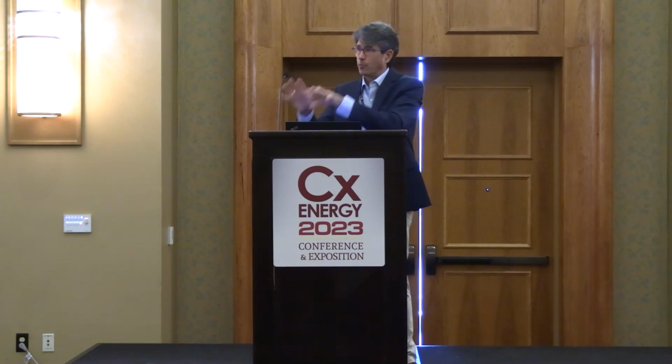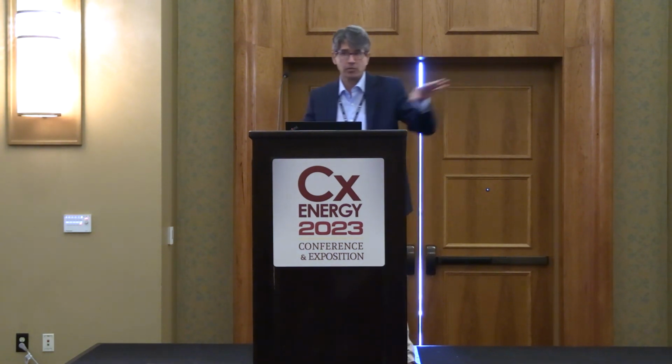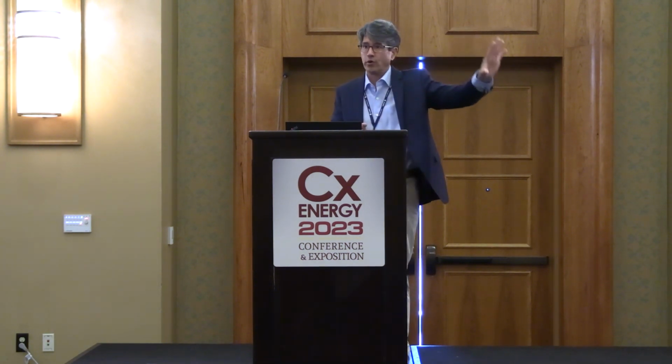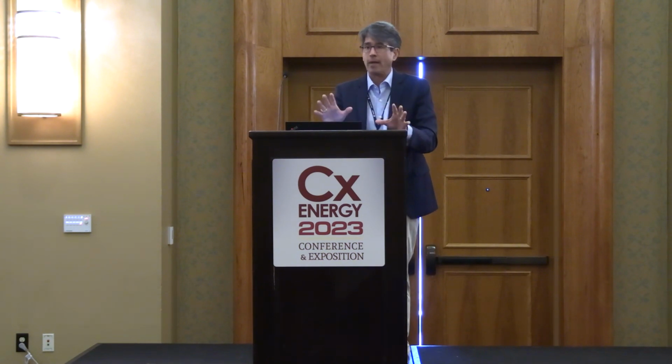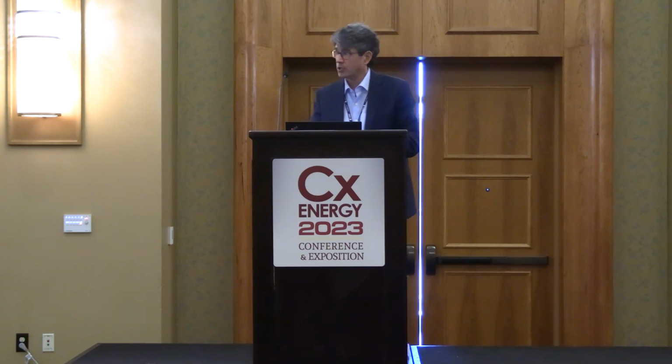We want you to measure all our pressures here, all our airflows here, the existing. We know we're making it now. When we add this after you balance it, we need you to go back and make sure we're okay there and that the system didn't affect that. So sometimes also the engineer wants to cover himself and say, hey, it was working before, here are the measurements, it's not working now, what happened? So that kind of scenario.